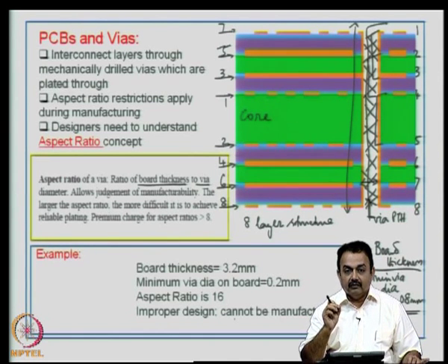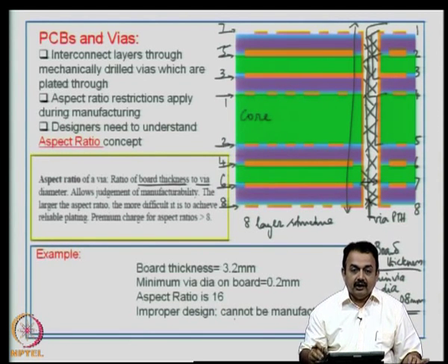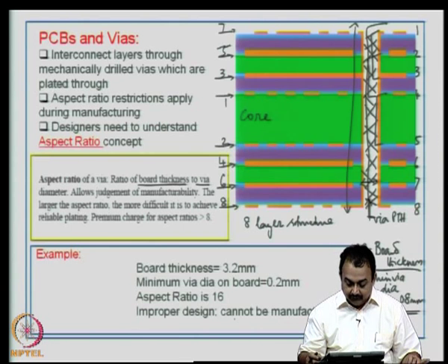are very thin, flimsy, fragile, and they produce a lot of heat during drilling. Entering through this 3.2 mm structure and coming out without breakage of the drill bit is a big challenge, because if you work at lower drill bit sizes, you have to increase the RPM of the drilling machine enormously.